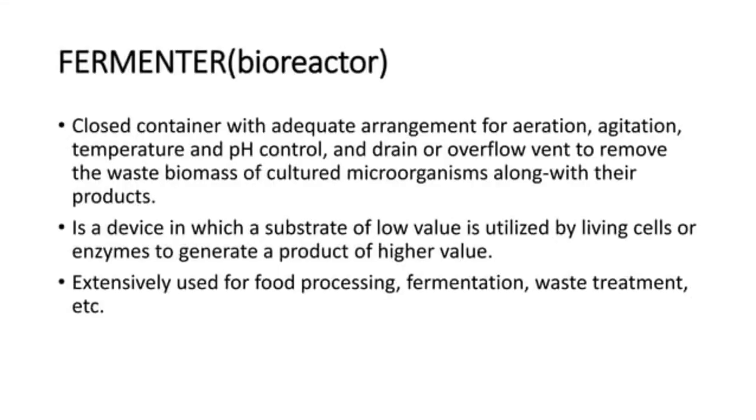Now, what is a fermenter? It is an enclosed container with adequate arrangement of aeration, agitation, temperature and pH control, and a drain or overflow vent to remove the waste biomass of cultured microorganisms along with their products. It is a device in which a substrate of low value is utilized by living cells or enzymes to generate a product of higher value. It is extensively used for food processing, fermentation, waste treatments, etc.